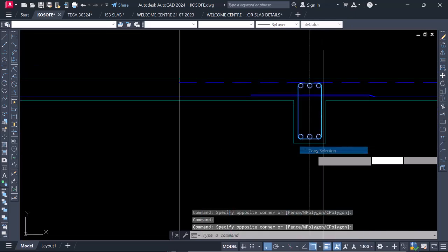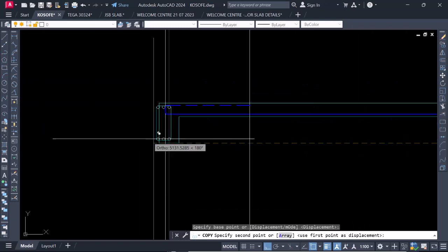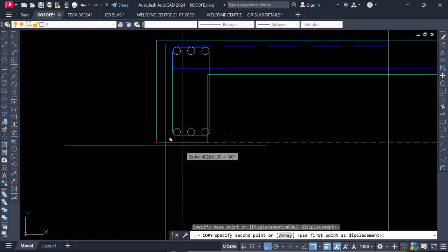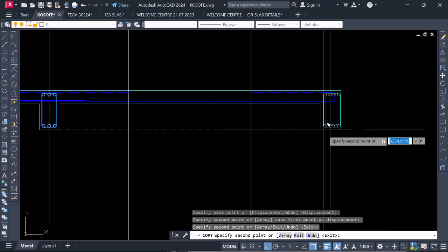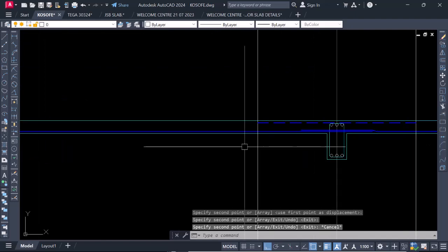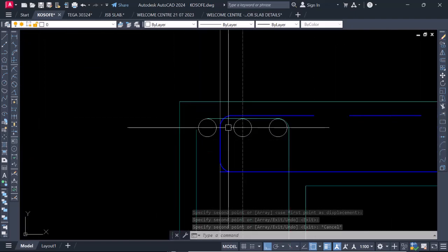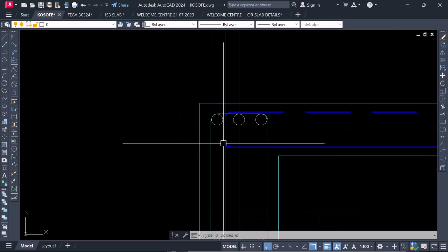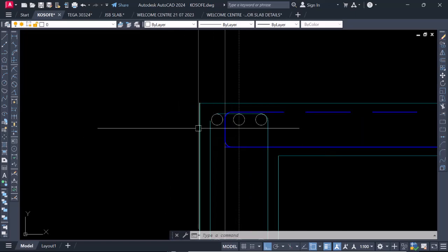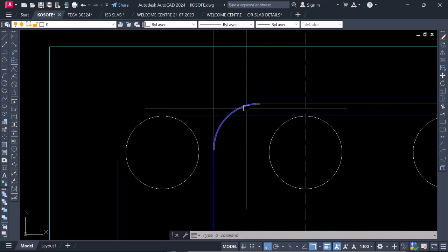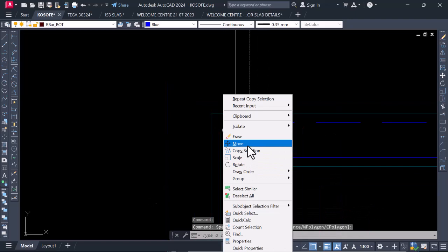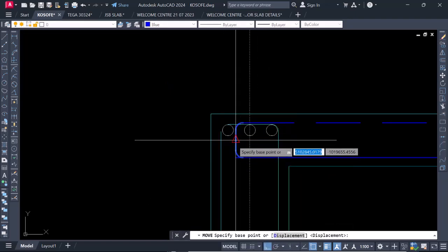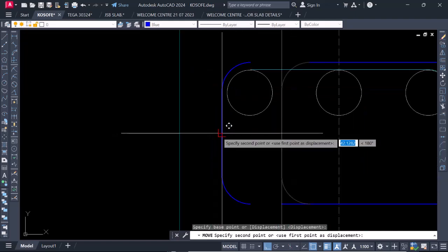All right, so what we're going to do, we're going to copy this from this point. Since we have the same width and the same depth of the beam, we are having the same strip running along the whole area. All right, so this is what we have. So you cannot have your lintel. Sometimes you can put it this way, but we can decide to push it behind. In most cases I see a lot of people putting it this way, but I recommend that we push it behind, right?